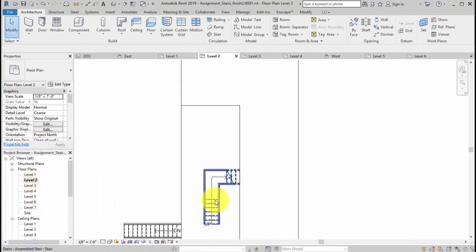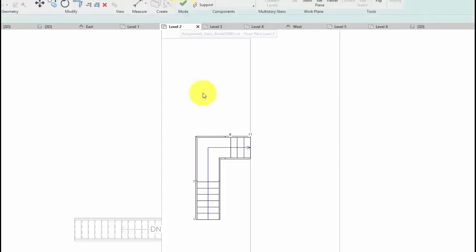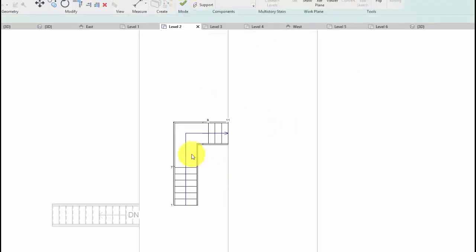We're going to create now the next one that actually reaches to the end. Okay, the next thing we need to do is create this split staircase. So here is the tricky part. We're going to select the stair. We're going to edit stairs. Okay, now next thing we need to do is run